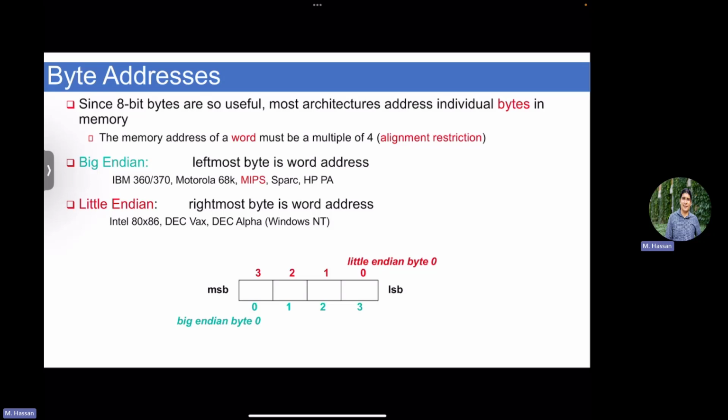But in reality, 30% of IPs in any SoC currently, whether it's in your mobile phone, tablet, iPad, it doesn't really matter, at least 30% are third-party IPs. So you have to go and purchase an IP from somewhere. Now there's an IP that best fits your needs, but it happens to be big endian. Your phone machine is little endian. Your choice to make is, should I really bother and buy it because it's very cost efficient and it fits my needs, and then I build a shim or a translator somewhere, or I should look for another IP or build it from scratch.